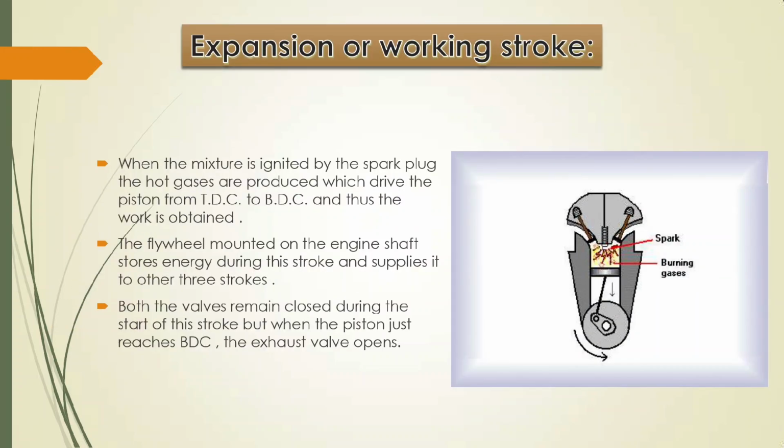Third stroke, that is called as expansion or working stroke. During this stroke, the mixture is ignited by the spark plug. The hot gases are produced which drive the piston from top dead center to bottom dead center, and thus the work is obtained. The flywheel mounted on the engine shaft stores the energy during this stroke and supplies it to the other 3 remaining strokes. Both the valves remain closed during the start of the stroke, but when the piston just reaches BDC, the exhaust valve opens.